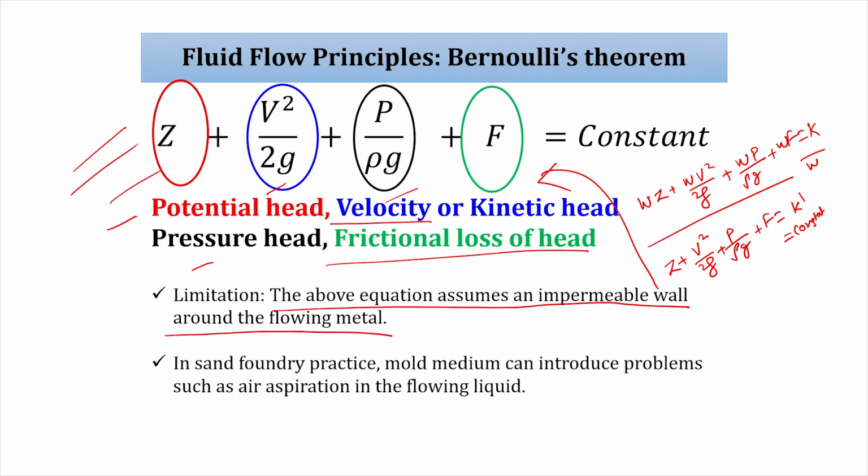In sand foundry practice, the mold medium can introduce problems such as air aspiration in the flowing liquid. This permeability can produce problems. So, we put in some assumptions to maintain this equation, to use it to calculate filling time. So, these are the assumptions.